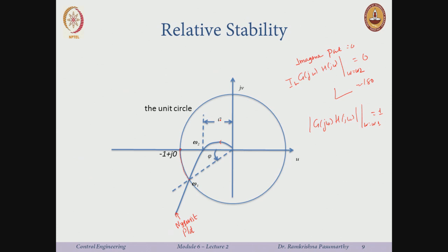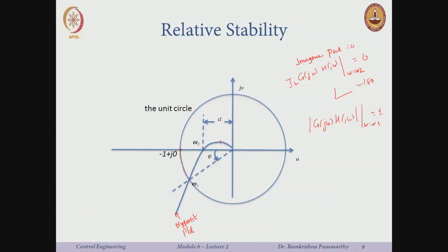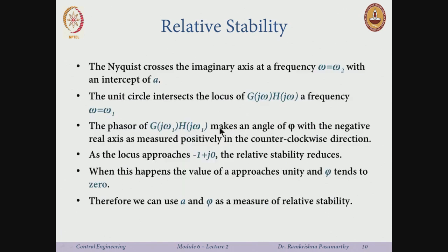So far I just said, okay, just be further from the origin in the S plane when I talk in terms of poles: if the poles are on the imaginary axis, the system is just marginally stable; slightly to the left, well, it is stable, but it is on the verge of instability, right. So, it is not very good, so now I can actually quantify these things. Okay. So, let us say these things a little more formally now.